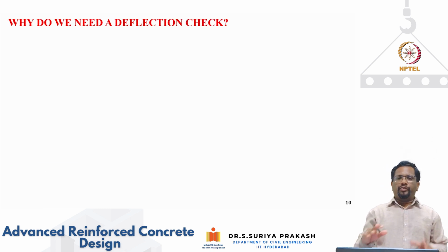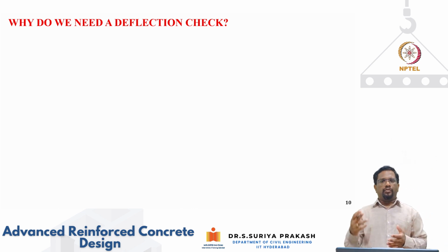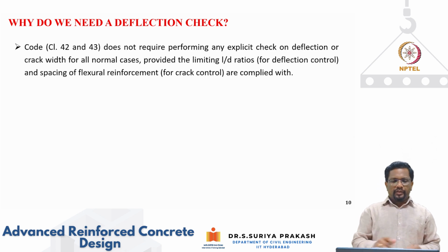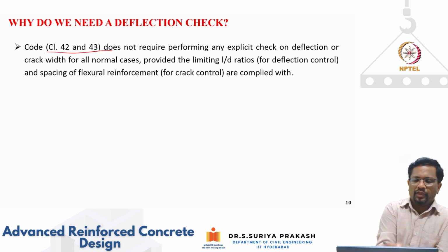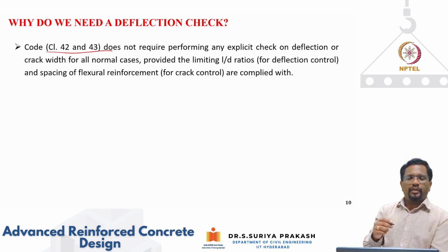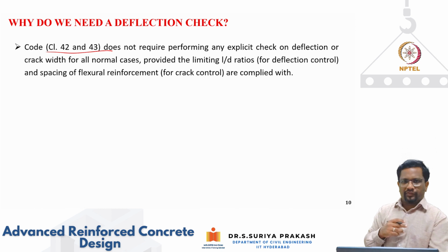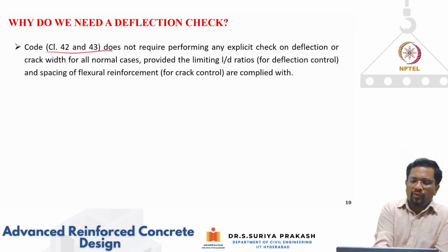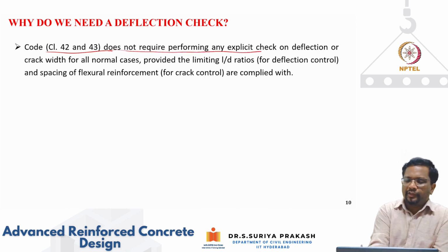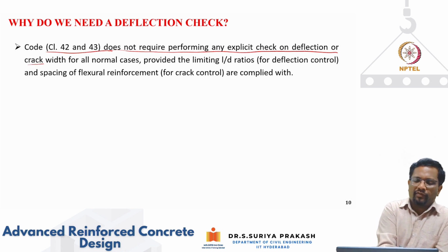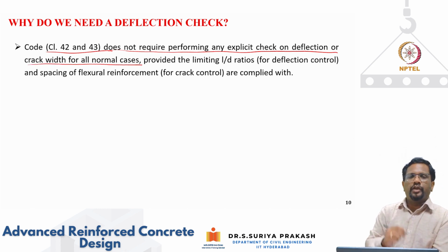Right. So now before we proceed, what is short-term and what is long-term? How do we check? Let's see, why do we really need to do this deflection check? If you look at clauses 42 and 43 of IS 456, it says that if you follow the provisions in IS 456, we don't need any explicit check on deflections or crack width for all normal cases, provided the L/D ratios that we have adopted for